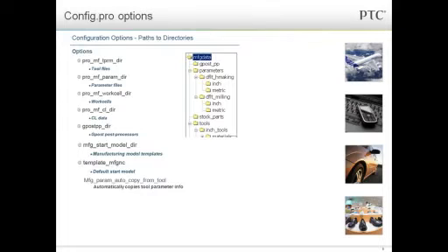And then what happens is, as long as you have your tool set up that has your parameters, it'll actually drive that information from your tool into your parameters, and you don't have to set that information up every single time. I've walked into a number of different companies where they have guys that are typing all that information by hand every single time, and it leads to fat fingering and crashes because you're going too deep, or an extra long time because you're going too shallow and you're recreating stuff all over. So there are ways to automate the parameter fill out. This is just one of them, and I just wanted to show this up here for config.pro options.